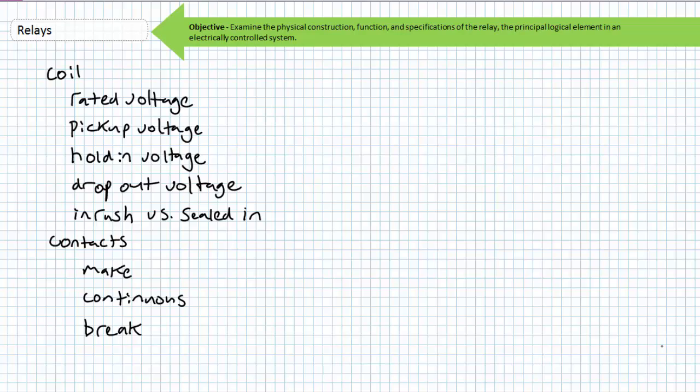Inductive loads like motors experience an inrush current several times their normal current draw. Similarly, pilot devices like coils of contactors, other relays, and solenoid-controlled valves experience an inrush. Relays switching these loads must be sized to accommodate this phenomenon during closure and open.